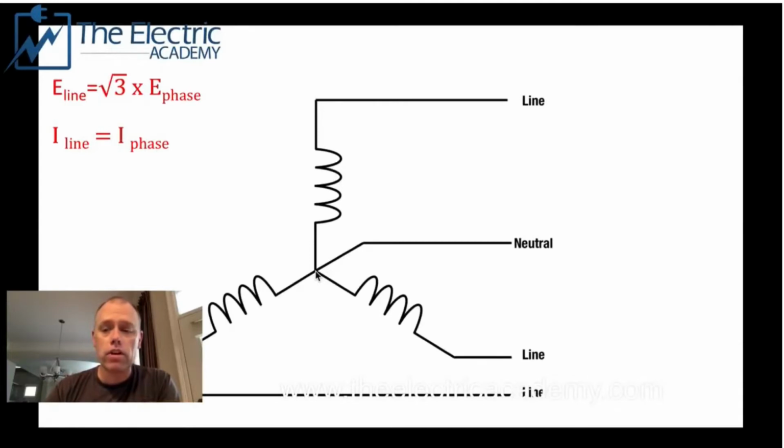It's good for unbalanced loads. It requires fewer turns than the delta type because you have a lower voltage here. You're using this voltage plus this voltage instead of having one winding carry all the line voltage. And you have less insulation too, because this voltage is going to be lower, but you can still get the 208 safely out of that. So it's very, very useful that way.